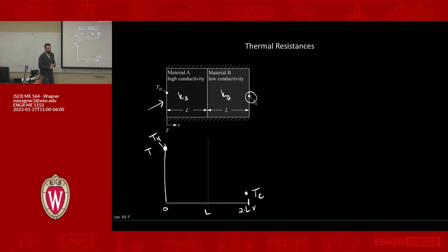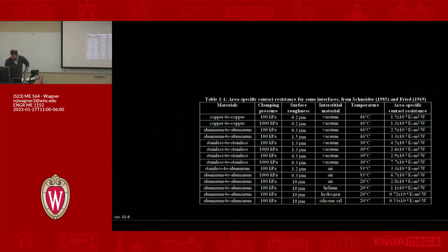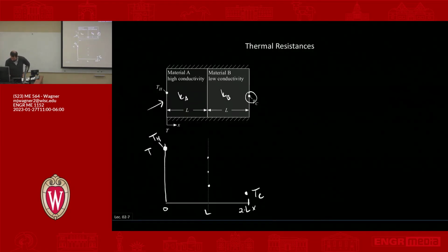First of all, this is a plane wall. Right? So in a plane wall, the temperature profiles are linear if it's at steady state. So the question is, I want to pick the temperature at which these things are going to intersect. Right? At the interface, there has to be a common temperature here. So would I pick this value, or this value? Remembering that K sub A is higher than K sub B. Yeah, why is the top one? Less temperature drop. Yes, exactly. Oops, sorry. So it's going to look something like this.